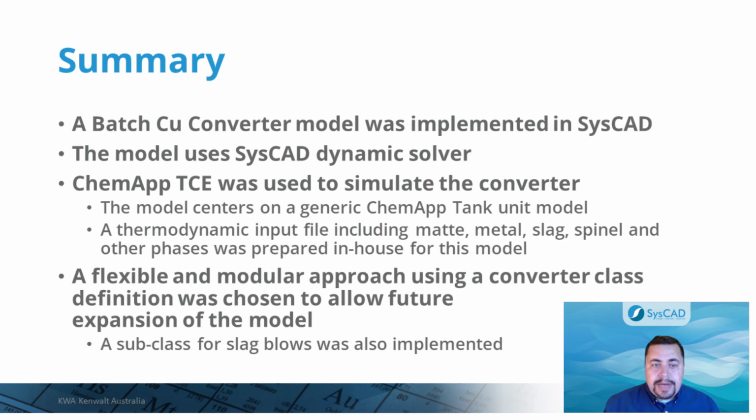To summarize, the bath copper converter model was implemented using SysCAD Dynamic Solver. The ChemApp TC interface was used to simulate the converter using a generic tank unit model with a custom-made ChemStage file for this system. In this case, a pre-programmed logic was defined where the converter class interacts with various input and output streams. However, the same principle can be applied to a model interacting with real-time plant data, either offline, reproducing past cycles to validate and calibrate the model, or as an online digital twin of a converter, providing operators with real-time estimates of key process variables such as iron or sulfur endpoints, or giving recommendations on flux strategies or